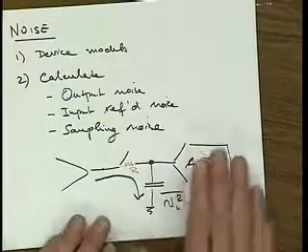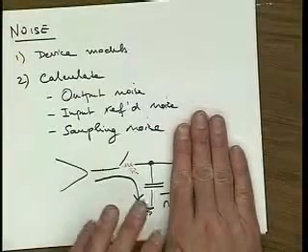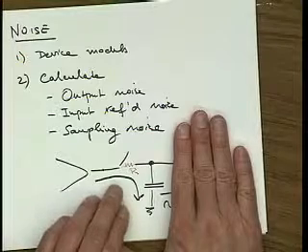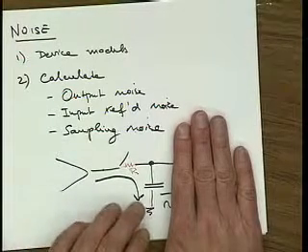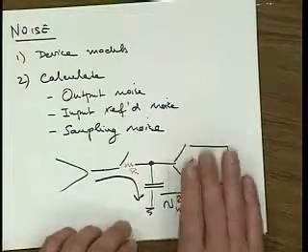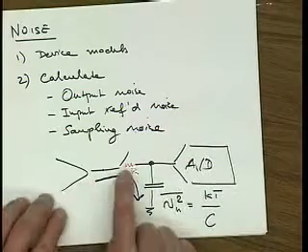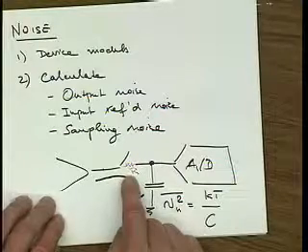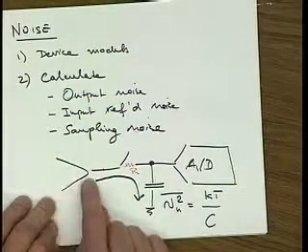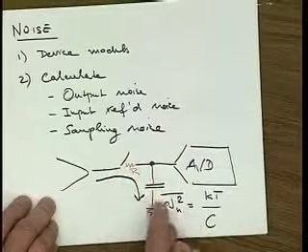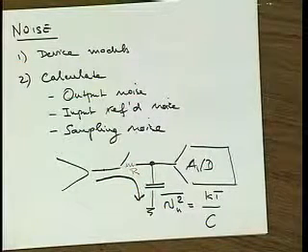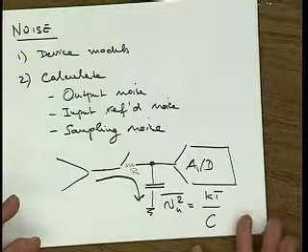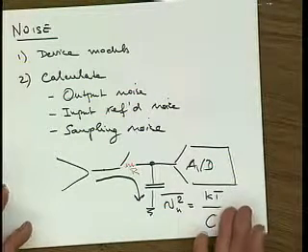So anyways, this is a very important structure, and we will see a lot more of it in 247, and we definitely want to know how to model the noise, right? Now, very often, and we're going to see examples of that also, not all the noise is coming from this resistor. This is an amplifier. It also has noise, and the noise from the amplifier really is making it to this capacitor. In that case, the equation, interestingly enough, looks almost the same. And we'll see plenty of examples of that.